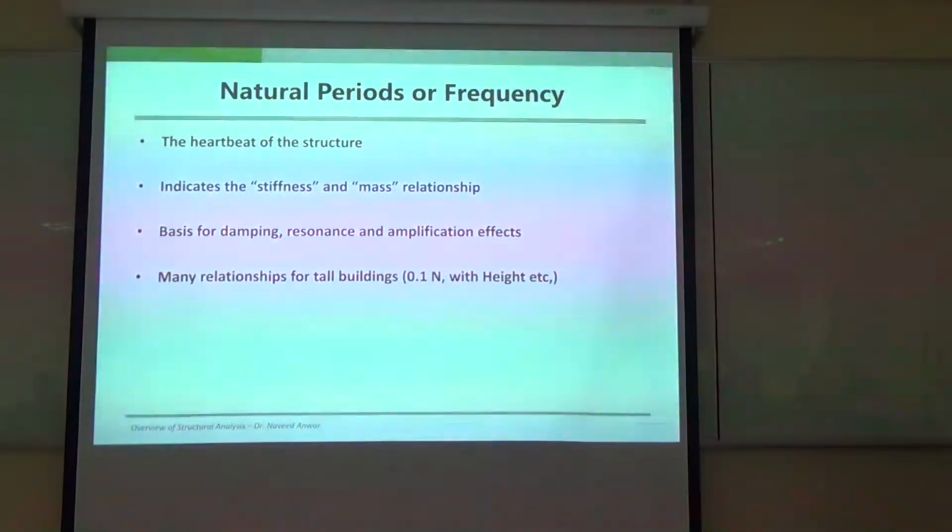Even a cell phone can be used. They have sensors now, acceleration sensors, right? So that data can be used to determine the natural frequencies. For example, if I put the cell phone here and I do it two, three times, then if the sensor is on, it can show you, and then from there you can find what is the natural frequency of this tabletop, right? So you can actually measure the natural frequencies by using the cell phone also now.